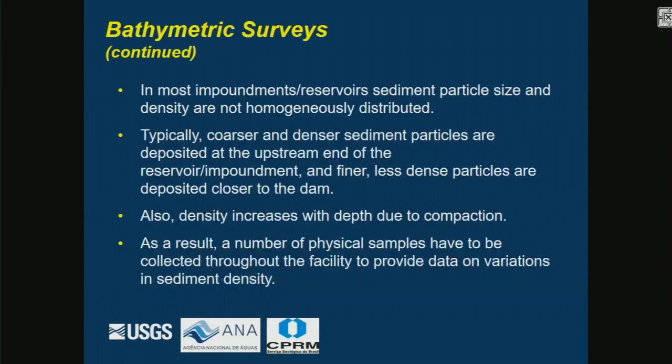That may be all you need, but if you want the mass of what's behind the dam, or you want to use that to calculate what's been transported in, then you need the mass of the sediment. So then you need the density, so you need some way to actually go down and get some sediment from the reservoir.